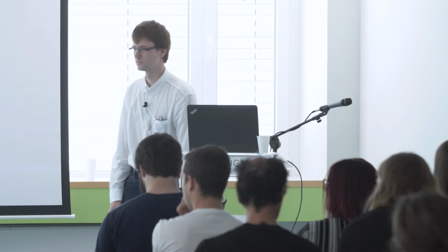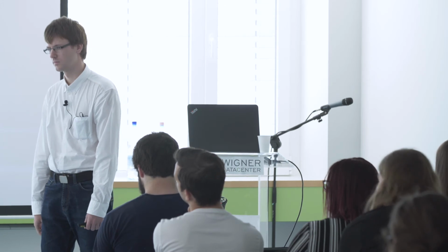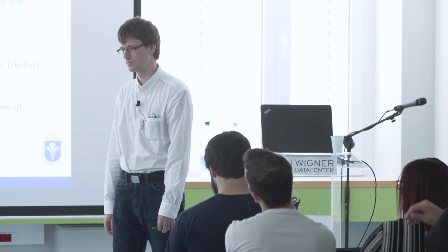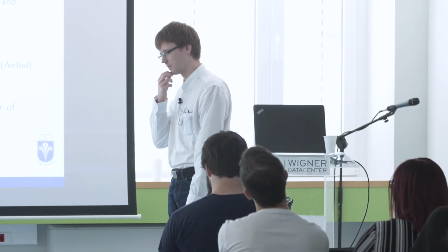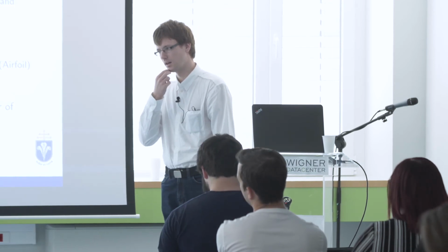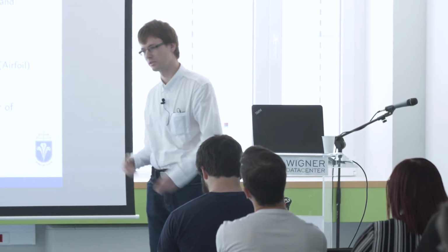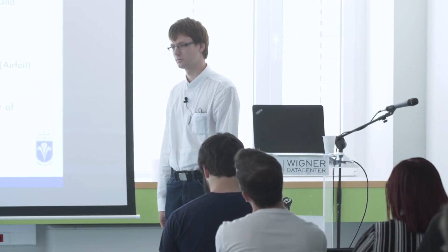Are these meshes dynamic or static during the calculations? These are static. And if I had a problem that required a dynamic mesh, and I needed to recalculate these colorings, how big a cost would that incur? The coloring algorithm is not the slowest part. The partitioning is the slowest, and I think the cost is quite high. That's why I put efficient partitioning code as a direction of future research. So at the moment, it's not really feasible.